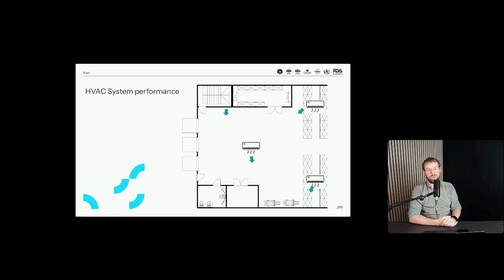So in the picture I have here, which is an imaginary warehouse, we have 3 HVAC systems that blow out temperature controlled air, and we have a radiator. So any type of heat or cold source is a risk that needs to be covered. And we need to be aware of which direction the air is being blown, or where it's radiated, or where that heat travels. So in the case above here, we need to take those risks into account and change our mapping protocol and methodology accordingly.